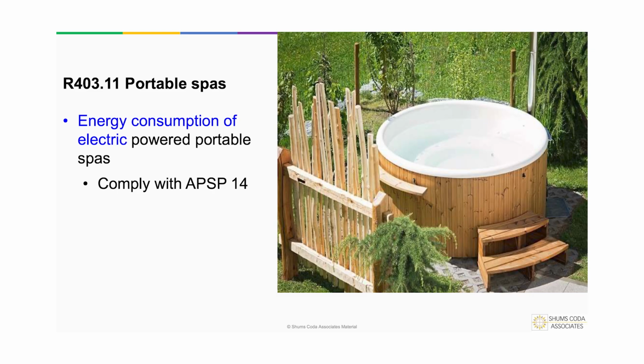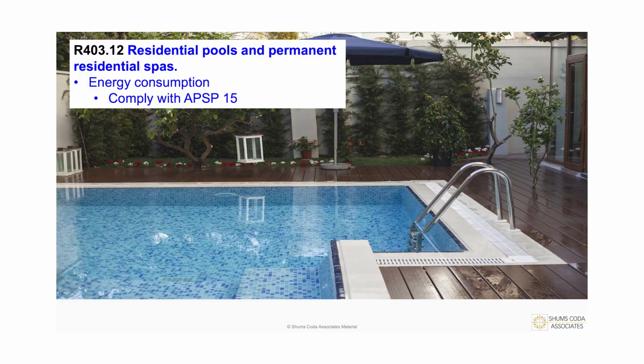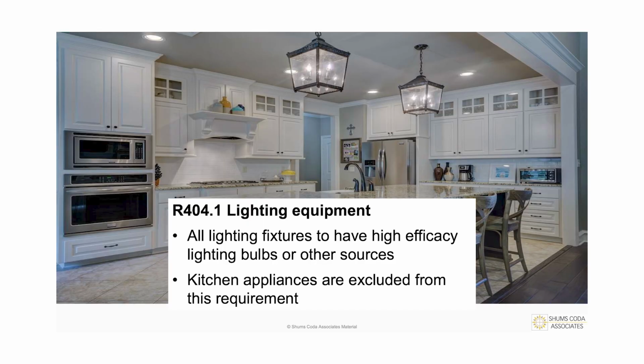All right, portable spas, they have an energy requirement too. They just have to comply with APSP 14. Now, residential pools and permanent spas, the energy consumption for these has to meet APSP 15. So if it's portable, 14. If it's in-ground or permanent, it is 15.